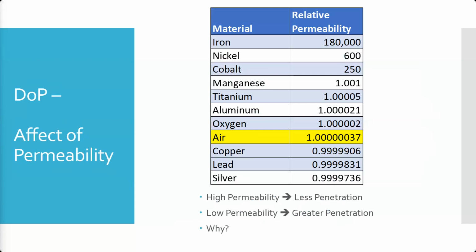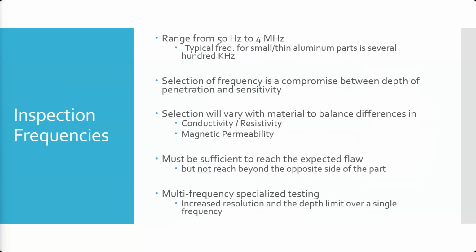Putting more power in it doesn't necessarily increase permeability or increase depth of penetration, because as it attempts to force that magnetic field further, you also get a stronger skin of magnetism forming, which prevents it from going deeper. So it kind of fights itself. You can increase or decrease the power to change things like sensitivity and how much resolution you get on your display, but it's not going to change your depth of penetration. Okay.